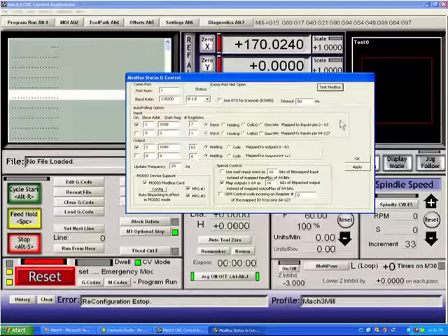And again, the low active settings do affect that. Same thing with the outputs. If you tell Mach3 to send up to 63 registers to the ModBus at this address that you have set, this amount of registers will be transferred to the ModBus control. Each 16-bit word sent will represent a 1 or a 0 depending on the state of that particular output. Again, port 0, pins 0 to 63.